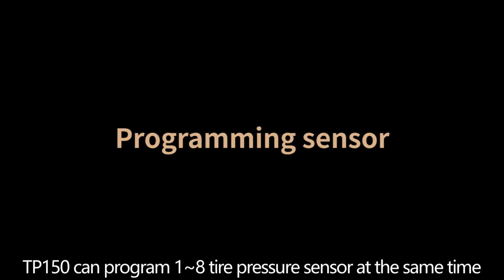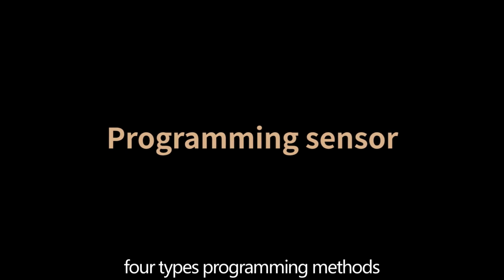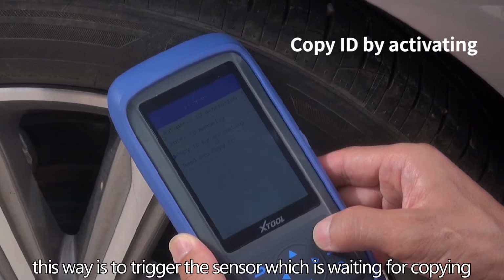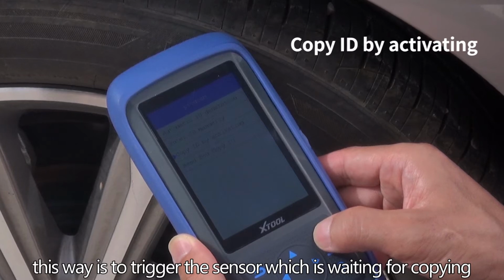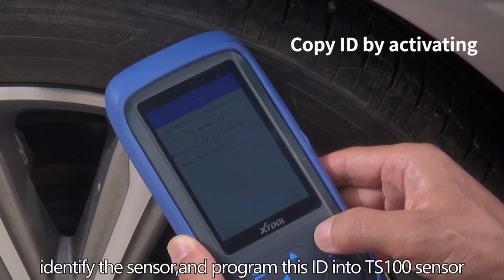TP150 can program 1 to 8 tire pressure sensors at the same time. There are 4 programming methods. First, Copy ID by activation. This way is to trigger the sensor which is waiting for copying, identify the sensor and program this ID into the TS100 sensor.